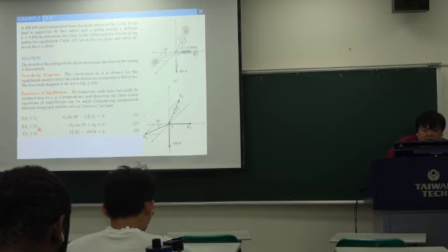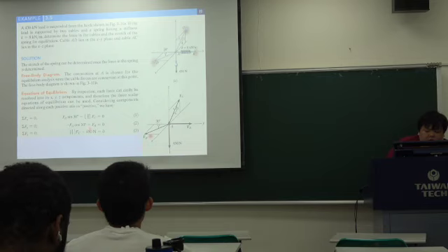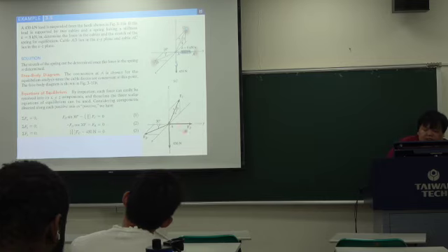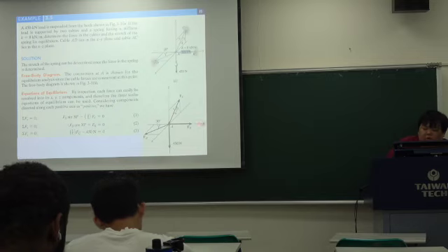Then in summation Fy equals 0, we use FD times cosine 30 degrees, then minus the loading force, and plus FB, because FB is in the y direction, equals 0.